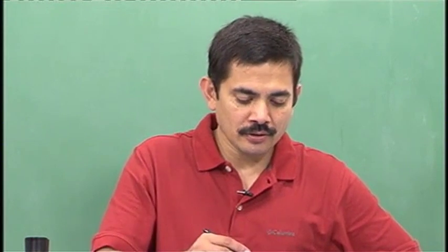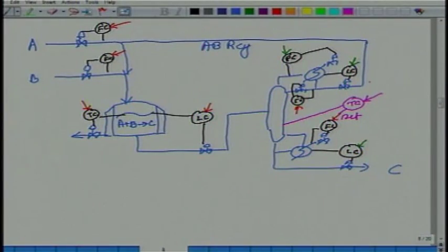He says, okay, we will control some composition inside the recycle loop. So let us say he controls a composition inside the reactor of, let us say, maybe A, and to hold this constant, what he does is, he sets the fresh amount of A being sent in, okay. Now tell me, is the overall material balance being respected with this control system in place, or will we still have some problem?